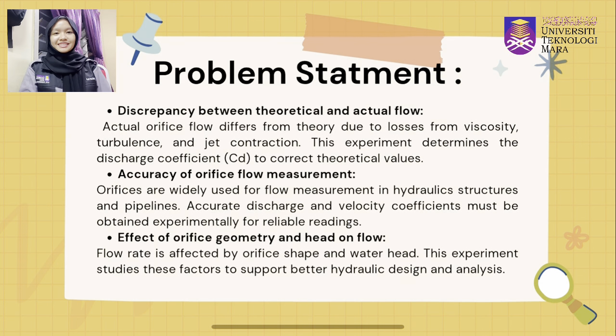Problem statement. First, discrepancy between theoretical and actual flow. Actual orifice flow differs from theory due to losses from viscosity, turbulence, and jet contraction. This experiment determines the discharge coefficient CD to correct theoretical values.